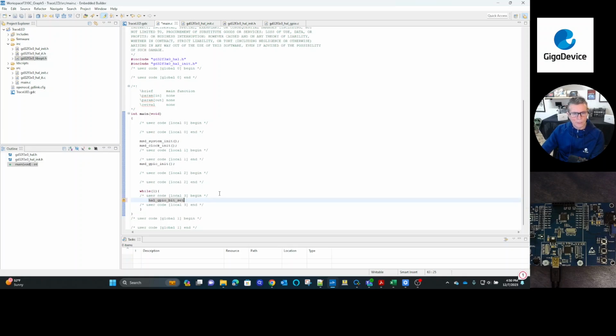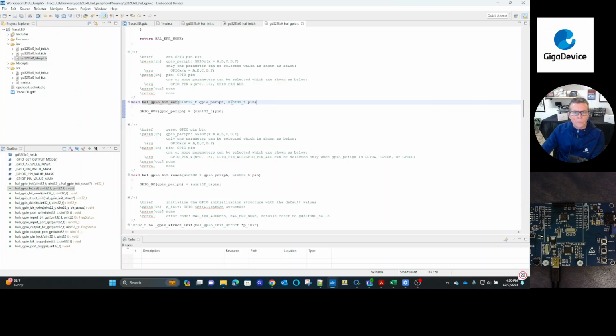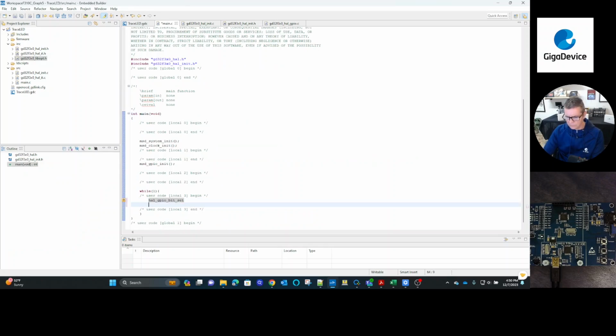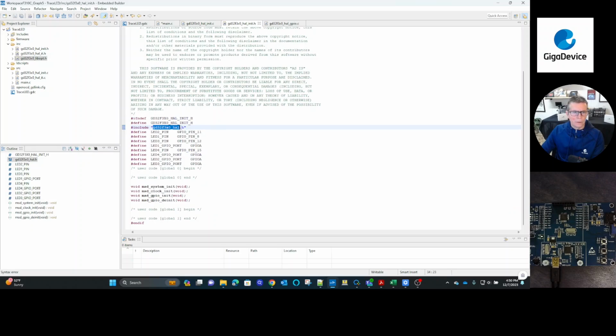So what were the arguments that we needed for that? If we go back there, we're going to set a breakpoint right here. Just copy the whole thing. The 2 variables we need to set up here are a peripheral, so a GPIO, and that was port A. And then we can actually use the pin name. There was a pin name created there. If we go back here, the pin that's LED.